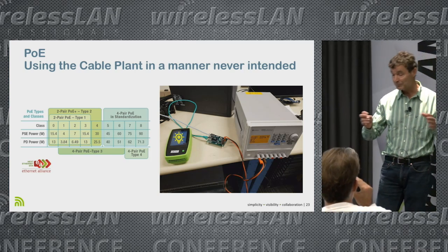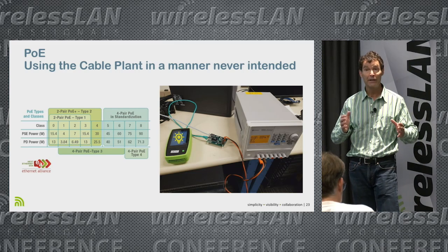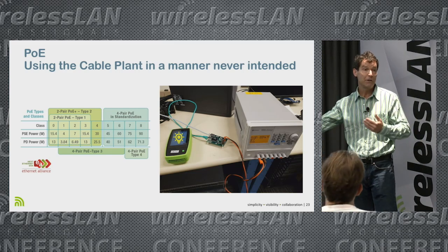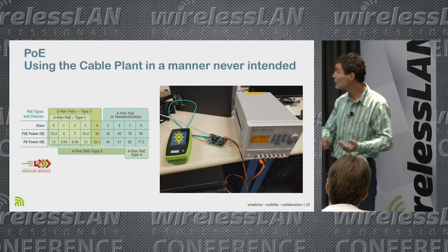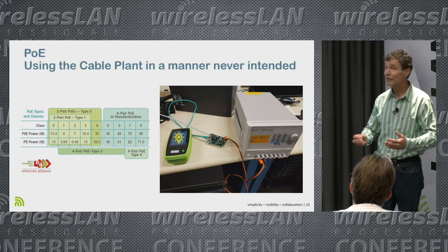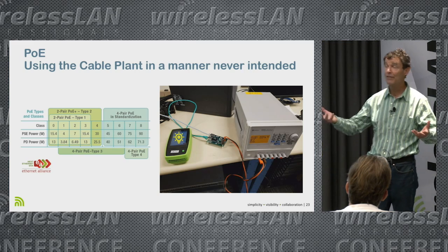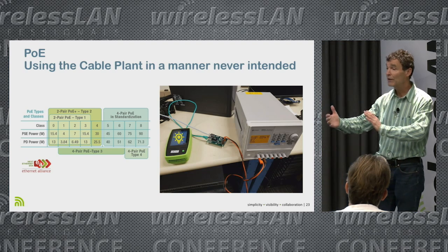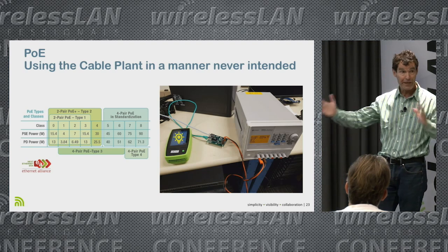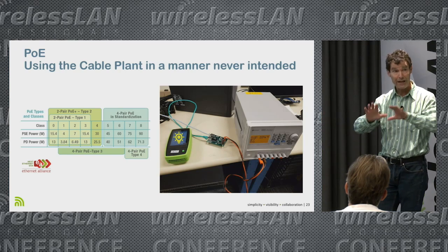Another thing is that when this cabling went in, chances are PoE barely existed, or it was providing 6 watts to a phone, right? Because Cisco kind of started the PoE revolution. Well, now we're basically sourcing 90 watts, and 71 watts is available at the PD, the powered device at the end. So I kind of went after this one too with the cable length, the cable coffin. But I wanted to take the switch out of the equation.